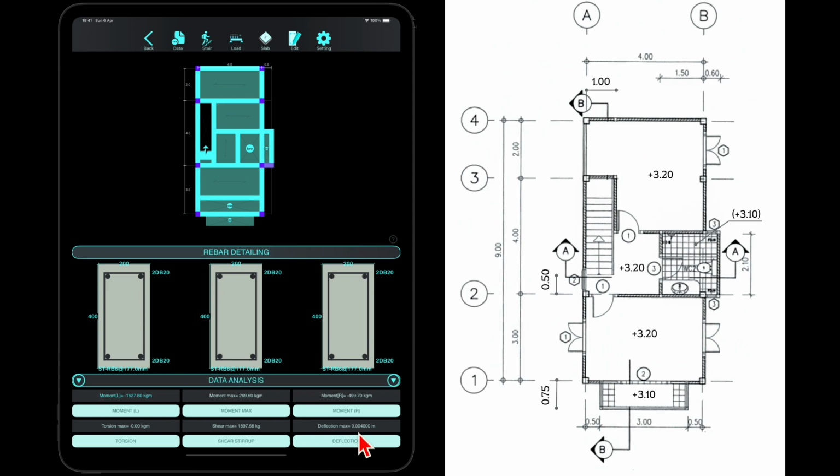The deformation warning shows only 4 mm, which is minimal. We'll leave it as is. However, if the system flags issues other than deformation, we must follow the recommendations immediately, as they could directly affect structural safety.